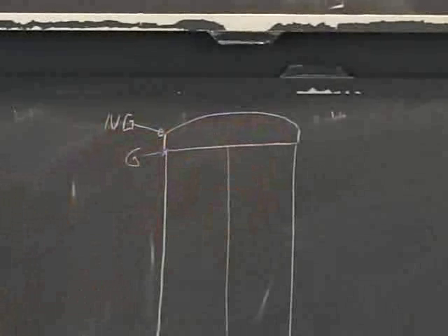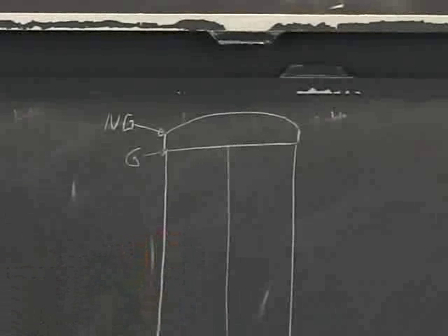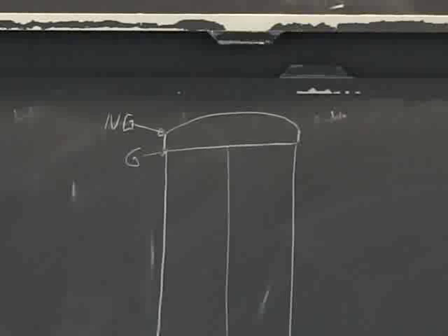It's a mistake that's done a lot, and I think it's important to keep in mind again that you could go and say, oh, I'm going to use very high strength steel, a 200 or 300 KSI strength steel to make a pressure vessel like this. But then you have to think about how you're going to put it together, and that's what we talked about last time with all the welds and issues with welds, because on a pressure vessel it's very rare that the pressure is going to be absolutely constant. So it will go up and down.